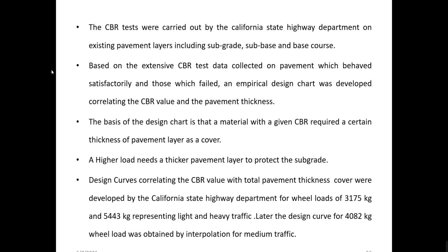Based on the extensive CBR test data collected on pavements which behaved satisfactorily and those which failed, an empirical design chart was developed correlating the CBR value and the pavement thickness. So they have consistently tested various different types of pavements, where some of the CBR tests were failing and some were passing satisfactorily depending upon the thicknesses.